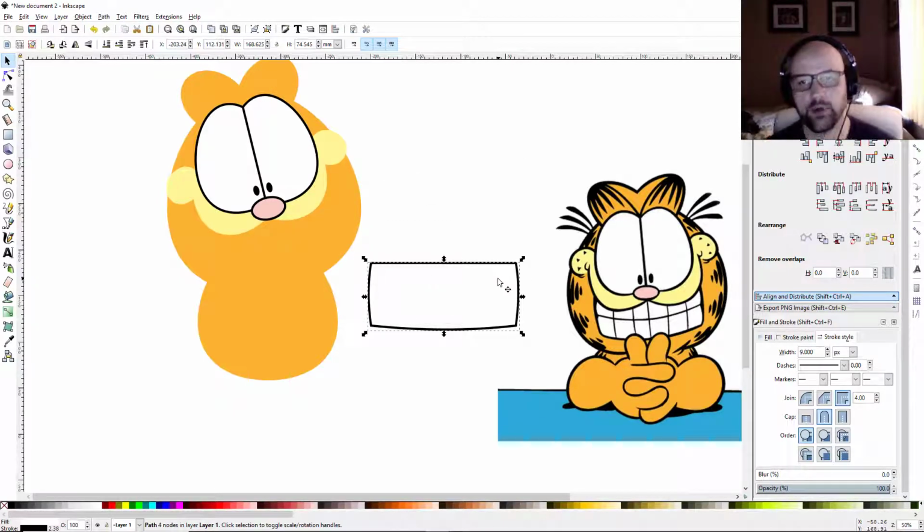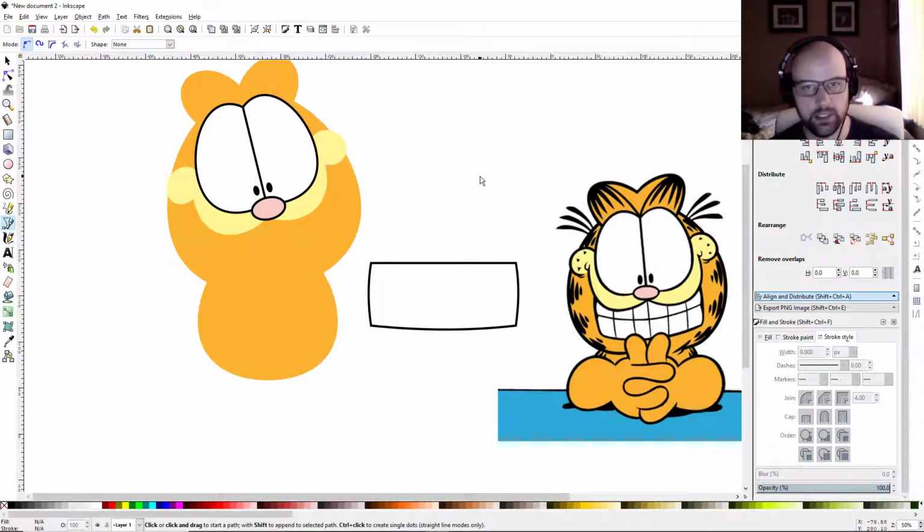and now what I can do is create the teeth for this thing. So let's grab the Bezier pen by hitting B on the keyboard and try to get as close to the halfway point as possible. You can turn snapping back on if you want to. And just click, hold control, drag this all the way over, handle the path, click it one more time and then hit enter.